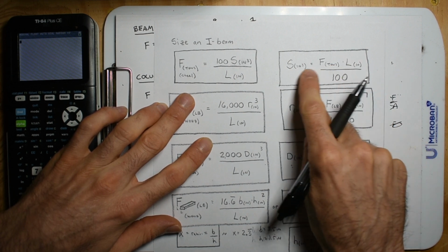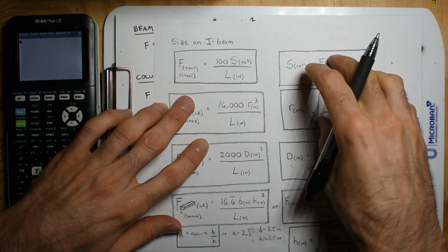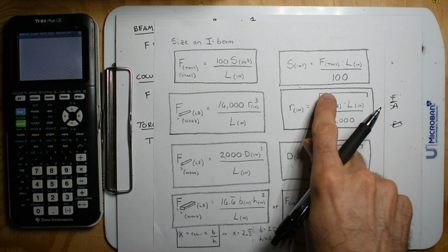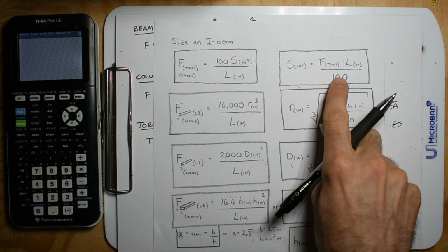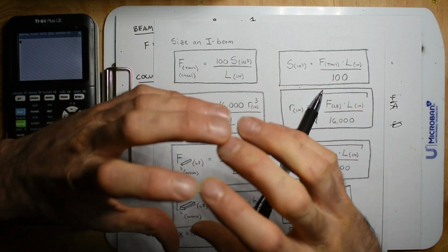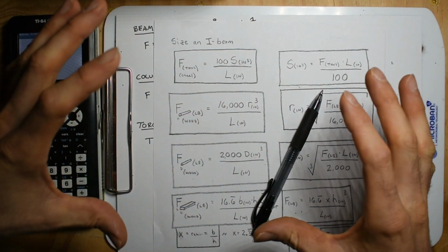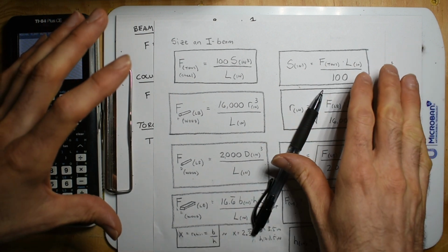So I need an S of 2, and then you just look up that chart and say, that's my I-beam. That wouldn't be too big of a deal. If you're only going 10 feet and you had chunks of steel shaped as an I for 10 feet, you could kind of visualize a car driving over that. So even just doing that